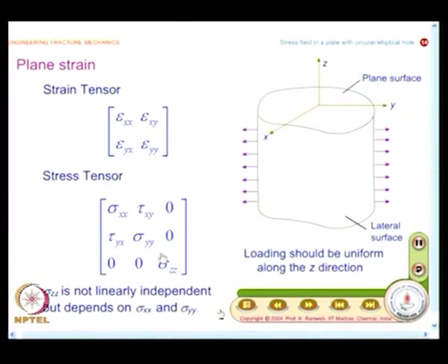So, when you look at the plane strain situation, you should recognize and understand physically the meaning of sigma zz. Here again, you go and look at what is the orientation of maximum shear stress. You must handle this problem as a 3 dimensional one. Similarly, look at plane stress also as a 3 dimensional one. In this space, what is the plane? That is very important. Right now, you go and look at and clarify your understanding.